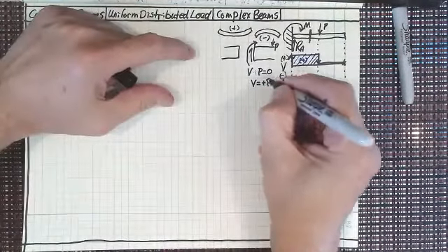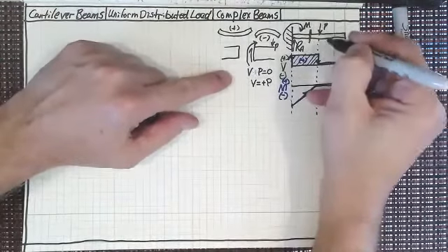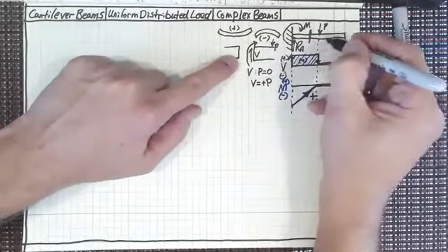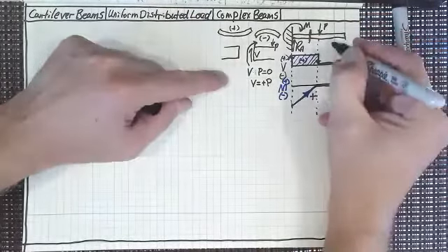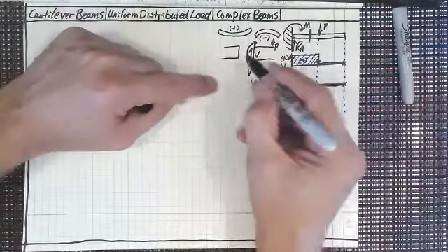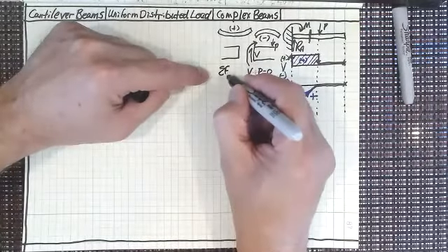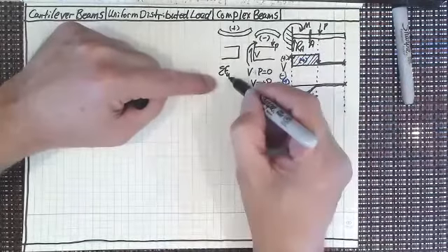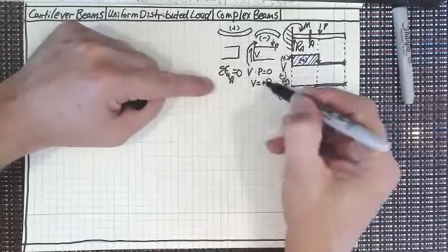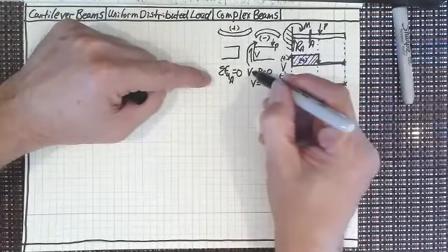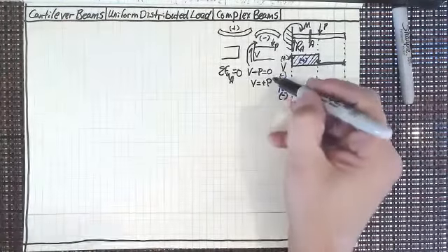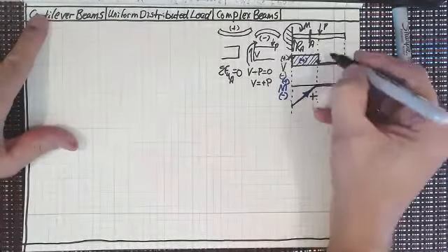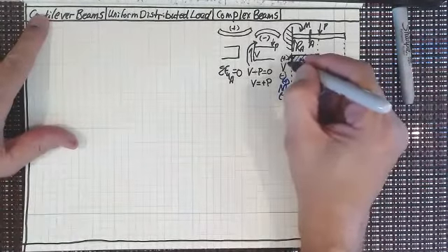So that's plus, of course, because P is going down, so it's minus, and V, let me just draw V in on this side. That's where we're doing the summation of forces. So that's what we've got, summation of forces in Y at point A equal to 0, tells us that it's V minus P equals 0, and so V equals plus P, and that's of course what we've got here, because what are we really doing? We're going up R sub A.